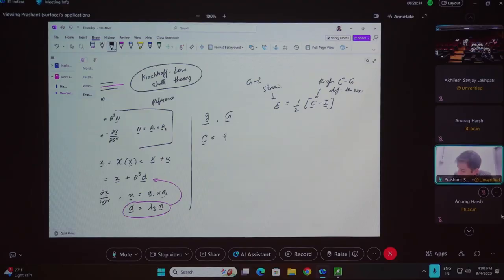So if you do things consistently, this is what you get for the case of the shell: the strain tensor is given as G alpha beta for the deformed, but then undeformed G alpha tensor product with undeformed G beta, plus lambda 3 squared G3 tensor with G3.